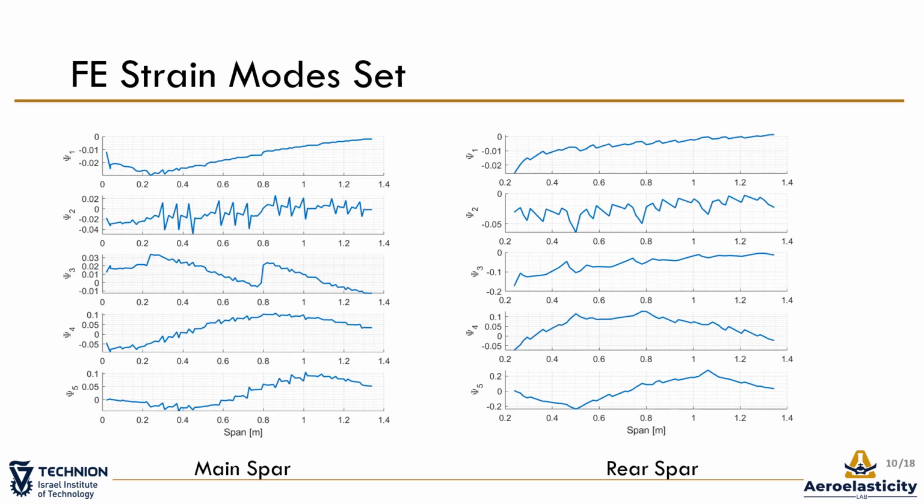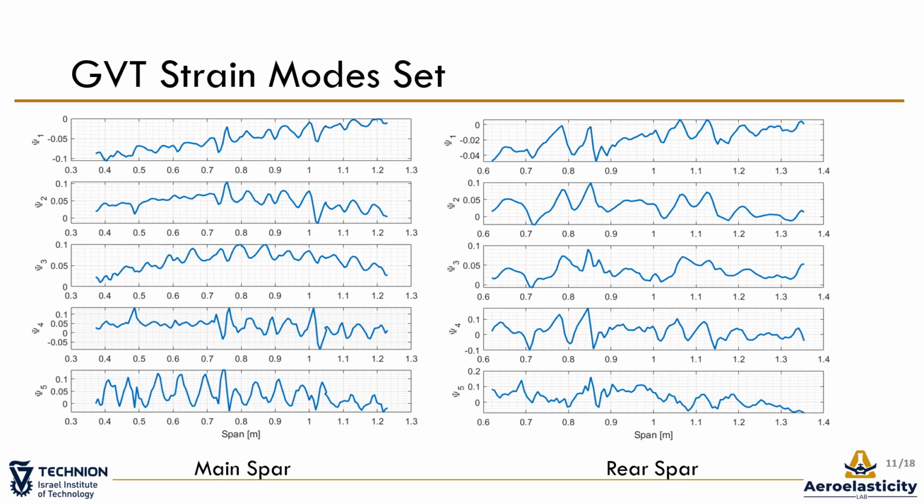Here are the first strain mode sets used in this study, computed with a finite element model. And here is the second strain mode set, computed from ground vibration testing, using strain response to impulse and the spectral POD algorithm. For more details, see the full paper.